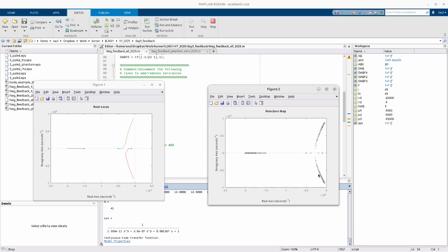Remember when we talked about stability in the first lecture? We said that the poles should be in the left hand side of the complex plane in order to be stable. In this particular case one pole is going to high frequencies and it is real, but the others are complex and are approaching the y-axis, so they are starting to give instability problems. So with a third pole, there is a possibility of instability; it deteriorates the stability.